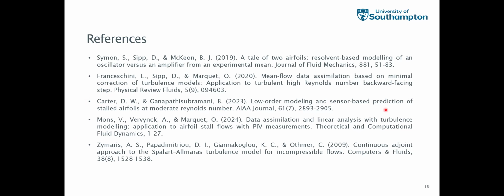I tried the field inversion case and also a source term in the turbulence transport equation for the Spalart-Allmaras turbulence model. In fact, I also tried the k-omega SST turbulence model, and in both cases I could not get good improvement. So we sort of ruled it out, saying it's possible that it's an artifact of the experimental data as such, and not the method itself.